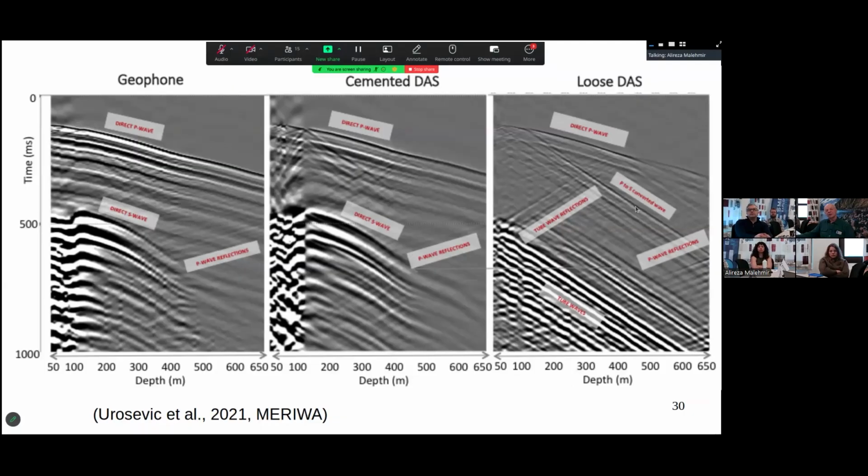They say this is a P to S converted wave, but I don't think so. If we look at this, it is a tube wave which is being reflected, and the slope of this tube wave is pretty much the same as this slope here. So I think this is actually a downgoing tube wave that was generated at some fracture zone in the borehole or porous zone.